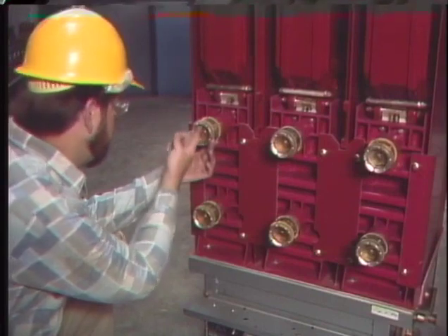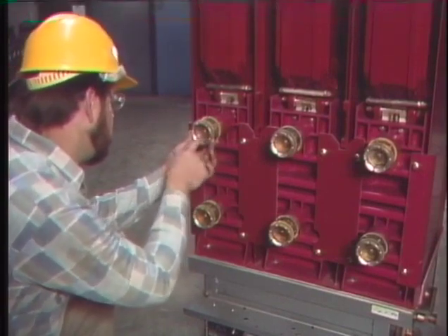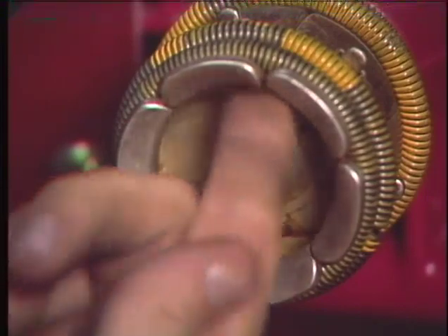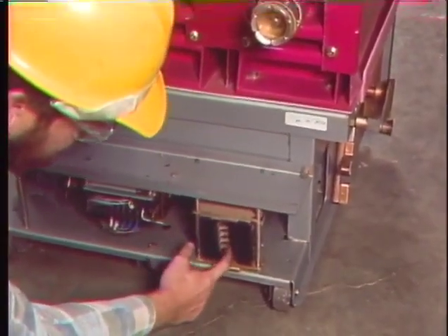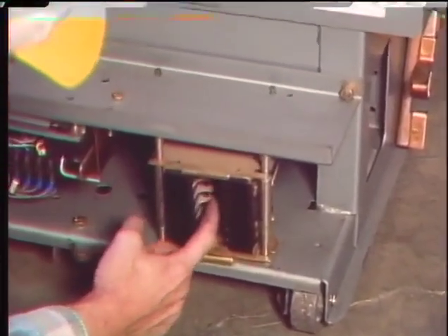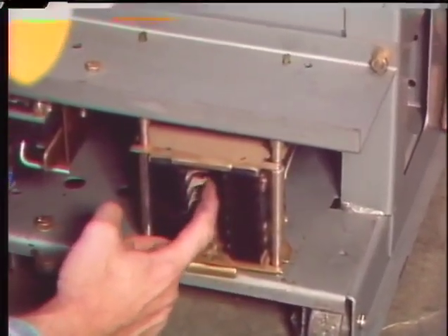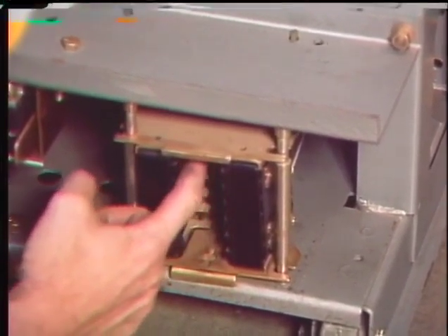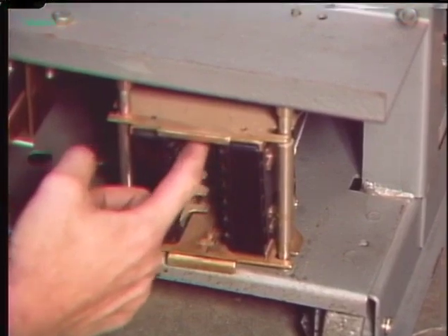The connecting surfaces are checked for uneven or excessive wear that may also result in a loose connection and overheating. The control power connections are inspected for loose, broken, or missing parts, chips, cracks, or corrosion. Any parts that aren't in good shape should be replaced before the breaker is put back in service.